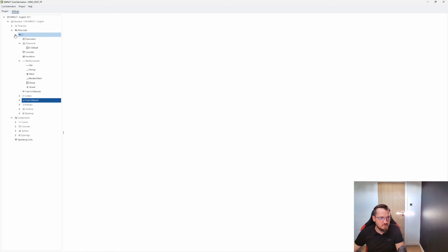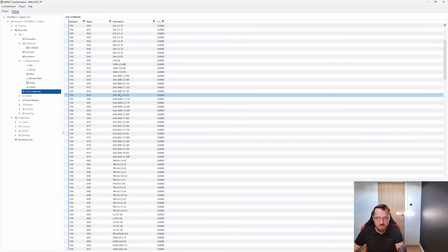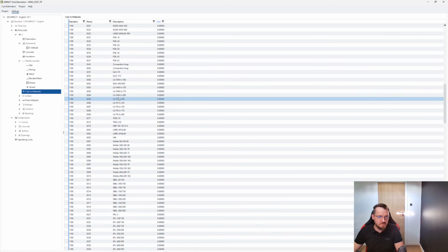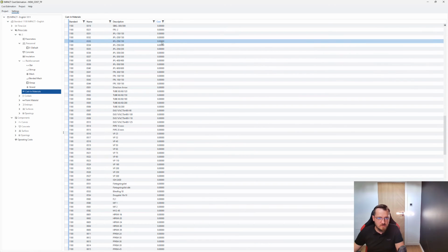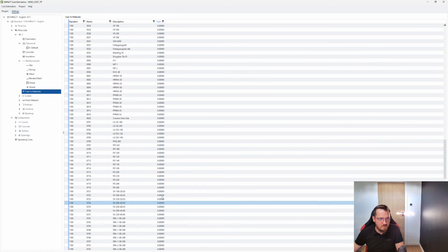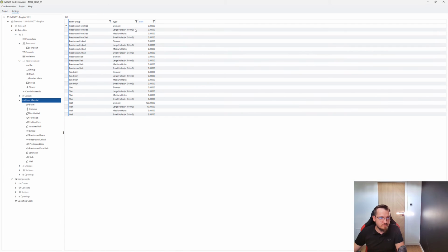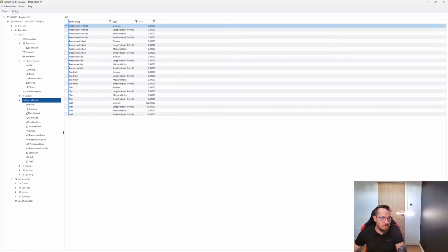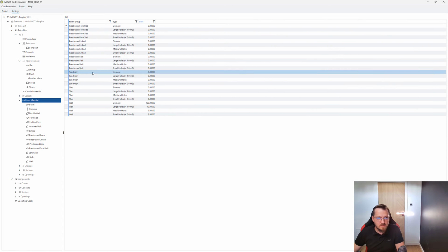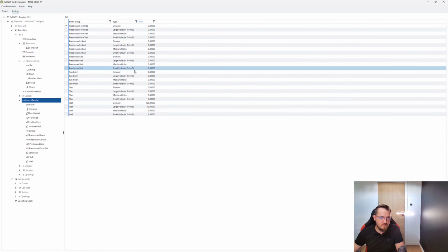And under price lists, if we go down, we can specify, for example, the cost of all the reinforcement, right? If we have any reinforcement in our model, the cost of cast-in materials. So here's the list of all the available cast-in materials that we have in our project, and we can assign some costs to it, right? We can also specify the cost of forms. So for both slabs, walls, sandwich walls, and whatnot, we can specify the cost per element.